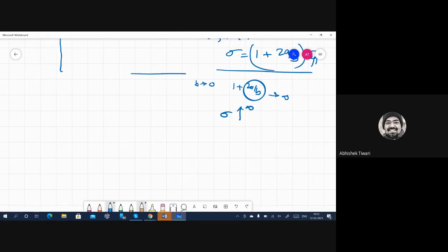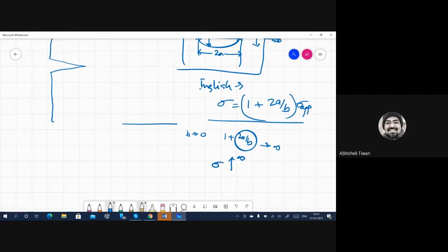So it becomes asymptotic. And for this, you don't need Irwin, or Williams, or Griffith, or anyone who discovered fracture mechanics. In the solution of Inglis, you had this already, that stress will become infinite at the tip if the crack is very sharp, if the discontinuity is very sharp.